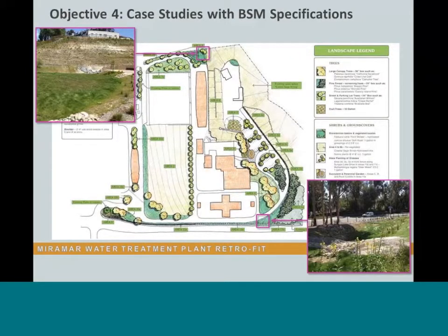And this was just one other project, a couple photos of bioretention facilities highlighted in the upper left and the bottom right here. This was a project that had to retrofit. The site had basically designed everything and built all their impervious area without their stormwater control measures or their BMPs. So it was coming in after the fact and adding curb cuts and creating bioretention areas, but getting the drainage into them was a bit of a challenge.